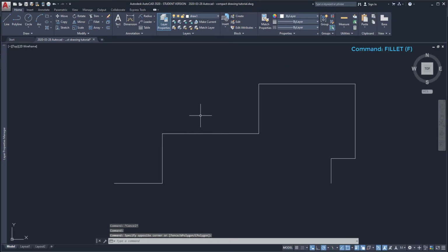I am going to show you to use fillet for all the corners in this polyline. It's really simple. Activate the command. Now it says radius 20. I leave it like that, but this time I want to use the option Polyline. Finally, I select the polyline and you can see that the command applied to all the corners at the same time.